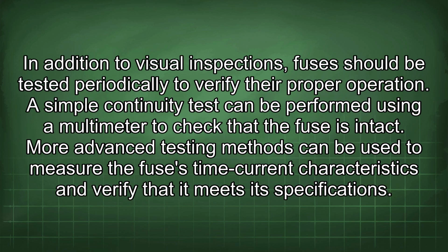In addition to visual inspections, fuses should be tested periodically to verify their proper operation. A simple continuity test can be performed using a multimeter to check that the fuse is intact. More advanced testing methods can be used to measure the fuse's time current characteristics and verify that it meets its specifications.